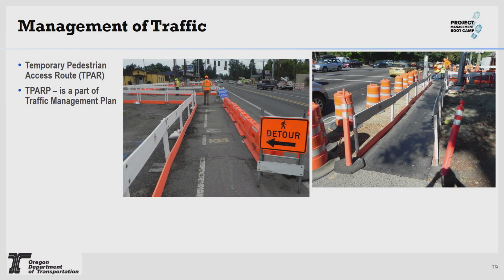In management of traffic, pedestrians and bikes are also a key part of traffic management. Traffic control plan designers provide the TPAR, temporary pedestrian access route, for construction staging. Sometimes the choice of construction material may be affected by the ability to provide TPAR or not. For example, if we have to open that for immediate traffic, probably concreting may not be an option, because